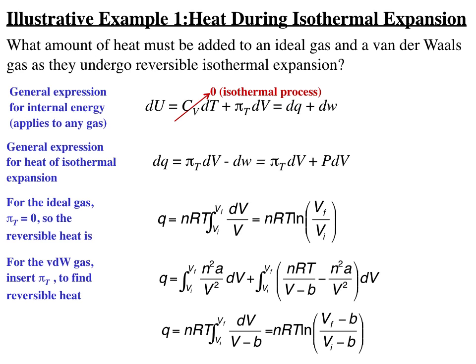If it's expending energy upon expansion, it should be cooling off as it does so. So in order to remain an isothermal process, the gas must absorb heat energy from the exterior as it undergoes this isothermal expansion process.